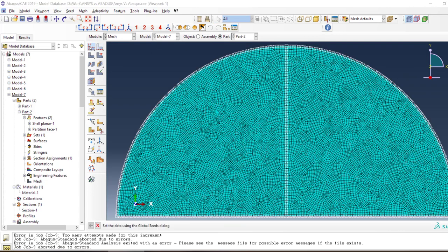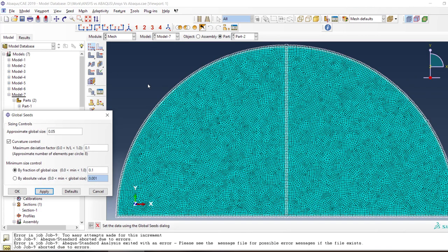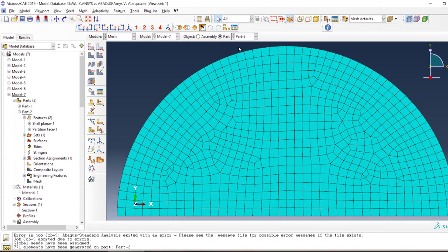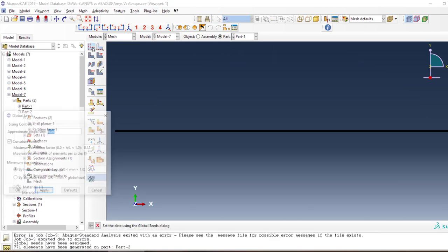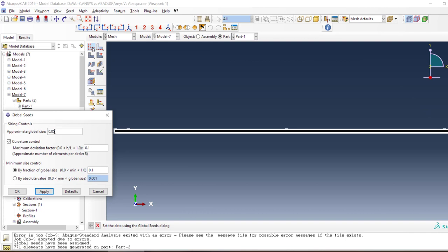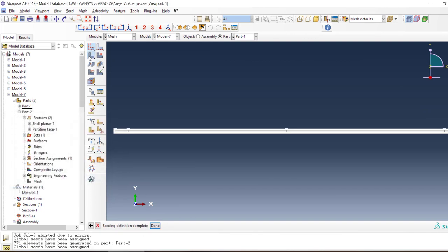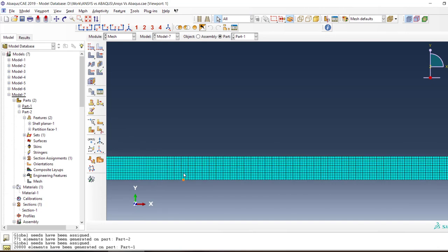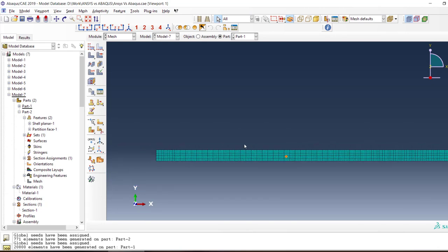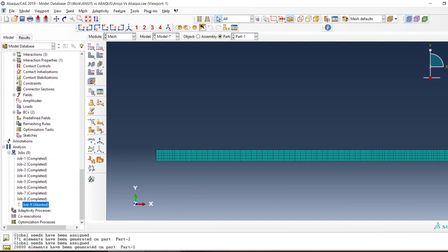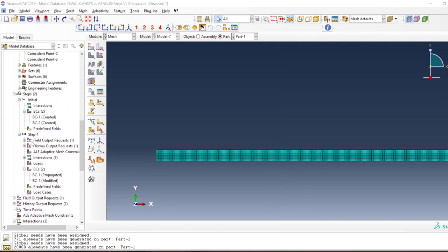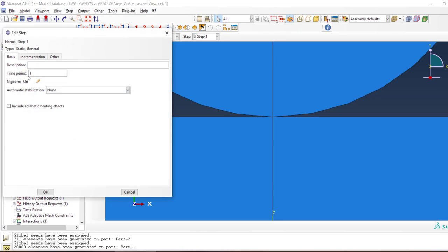but I can reduce the mesh by making the problem a little bit smaller, 0.05, and enter, and then you go the same size, 0.05, and so we spend less time computing and more time on troubleshooting. Yeah, it's still too fine, and we can check it. Yeah, that's good.